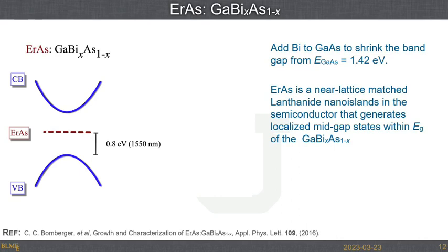So he's doing that on a couple of samples, but the technology would scale up to something that we do for this as well. Because you wouldn't need just one chip there, you'd need millions of them. Chemically, what this does is, because the erbium arsenide isn't directly integrated in the gallium arsenide, these appear to be localized states. These appear to be almost like artificial atoms that are placed inside the gallium bismuth arsenide material.